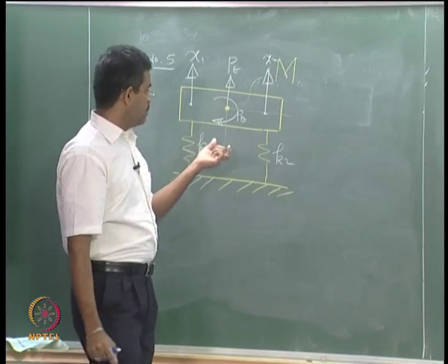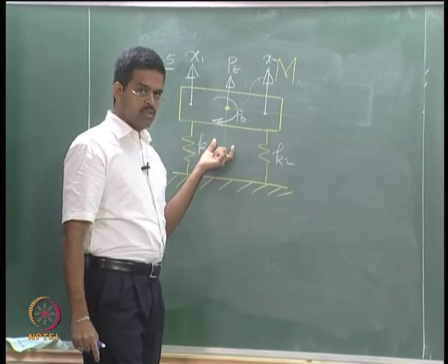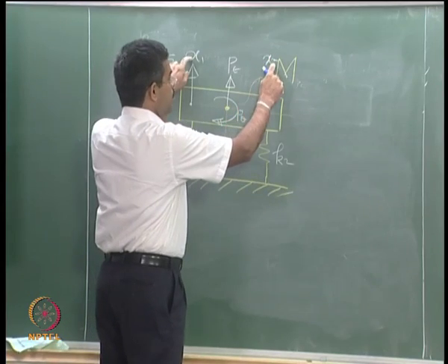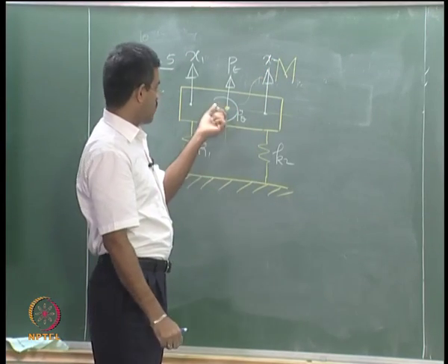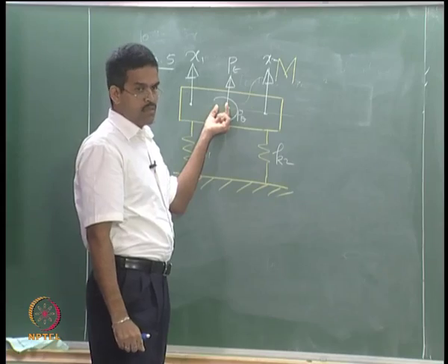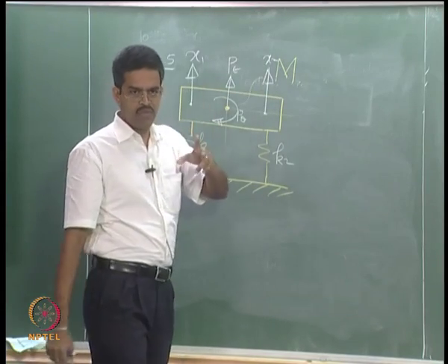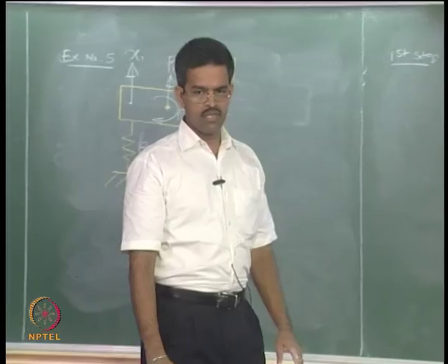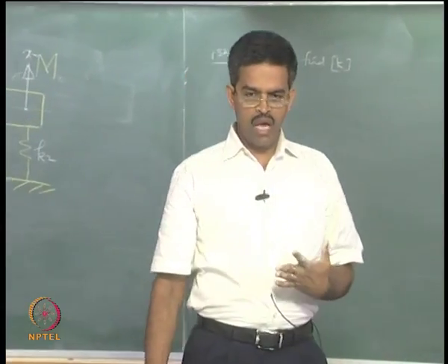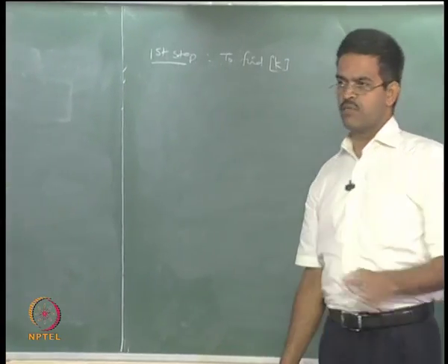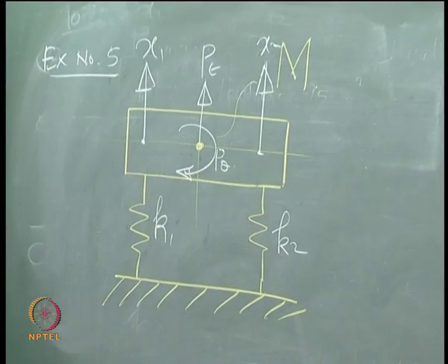It also implies a very important conclusion. Degrees of freedom are not the points where the mass is lumped. Here I have got only one point where the mass is lumped, but I have 2 degrees of freedom. I think we cleared this carefully in the previous definitions. So we can always have a shortcut saying mass points are said to be the degrees of freedom, but it is not always true. For example, in this case,